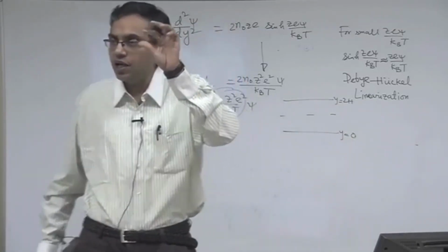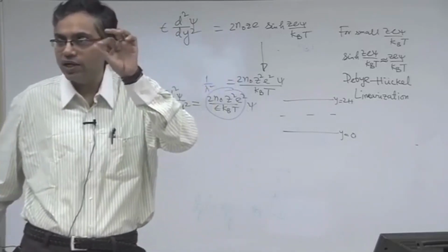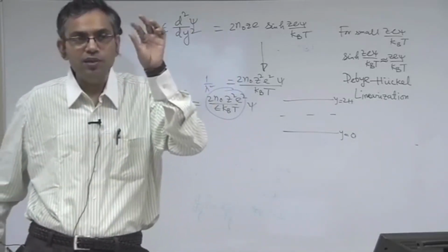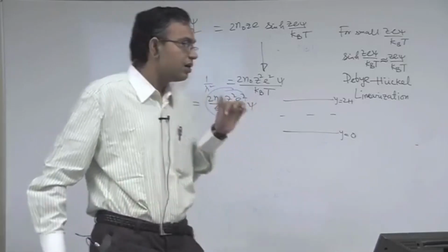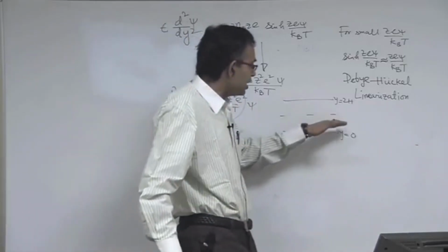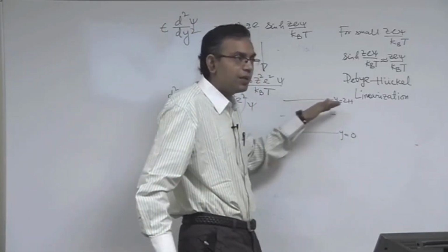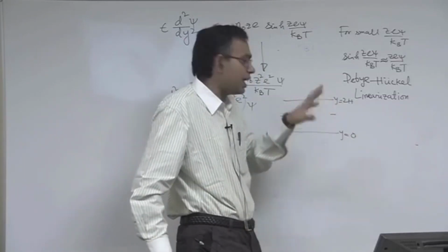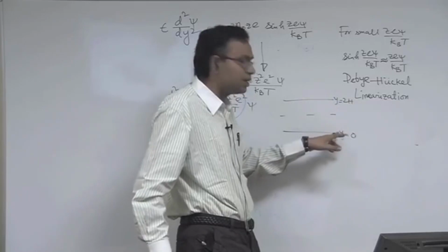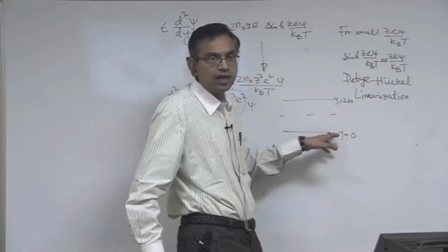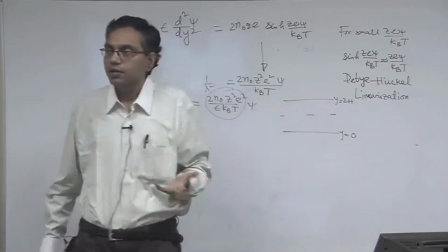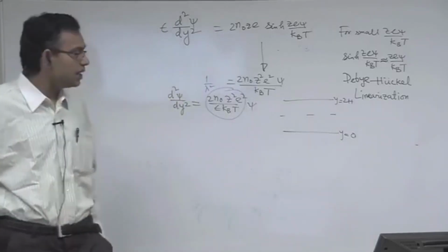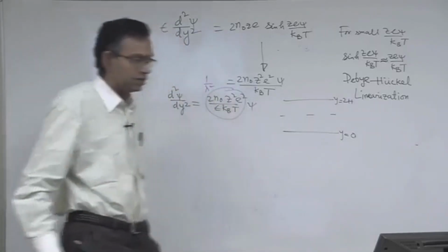But because the shear plane and the solid boundary are located just a few angstrom apart, and not only that, when you are thinking about fluid flow, you are basically giving the boundary condition at the shear plane. So keeping these two factors into account, we approximate this by the zeta potential. So that is a standard practical interpretation for giving the boundary condition.